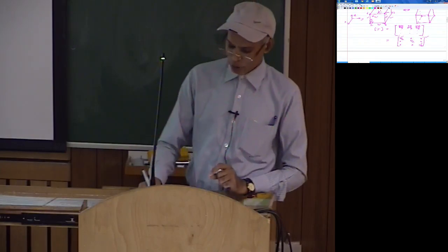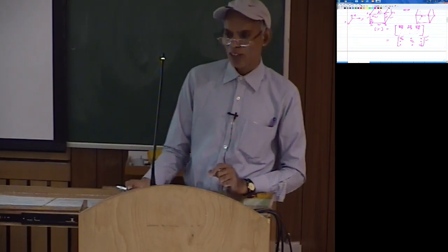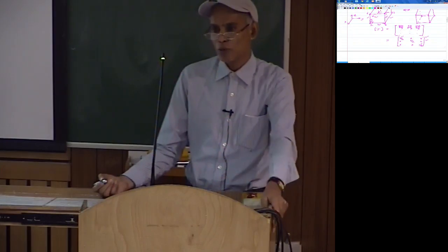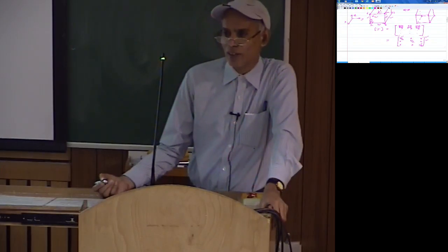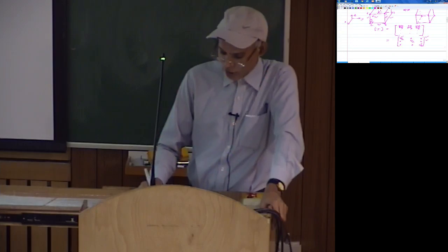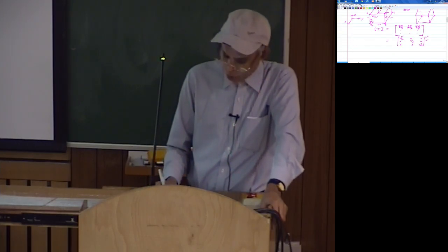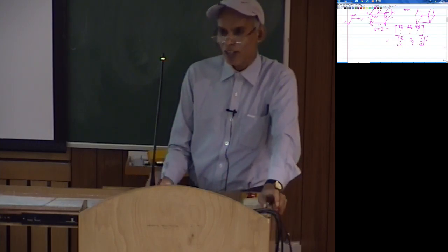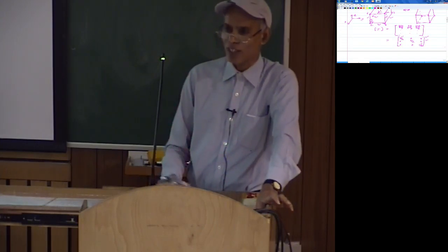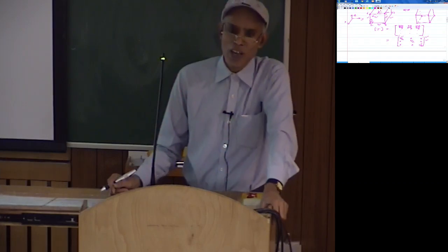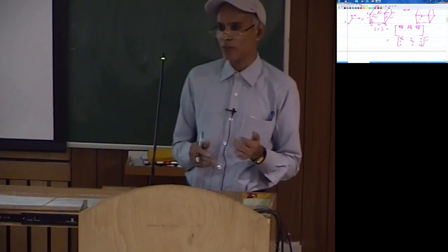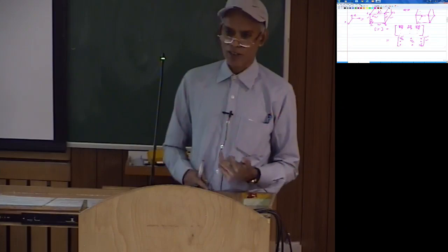Then when we try to invert this J, the Jacobian matrix, it would be a nearly singular matrix, which is referred to as an ill-conditioned matrix. So we cannot have very large ratios of A, B and C. Ideally they should all be equal to 1, that is the best, but obviously we cannot have that because structures have different dimensions in different directions.